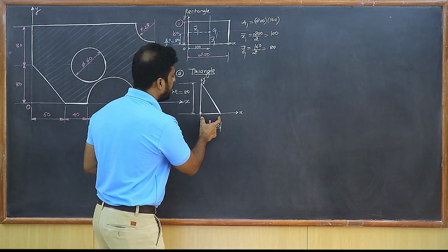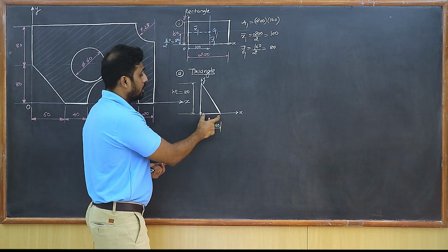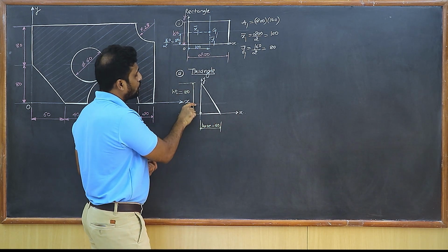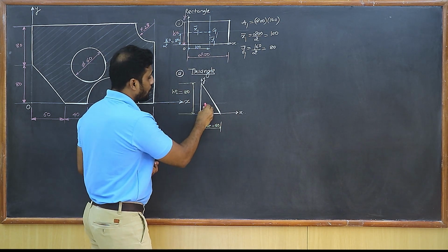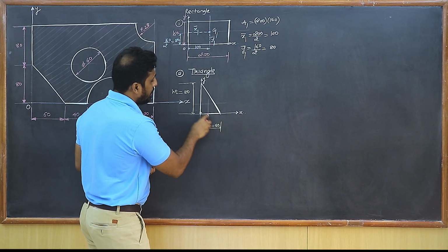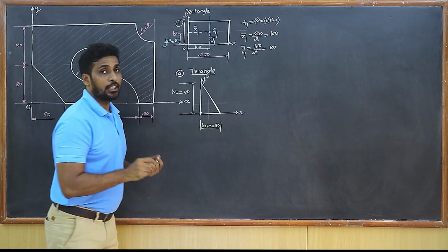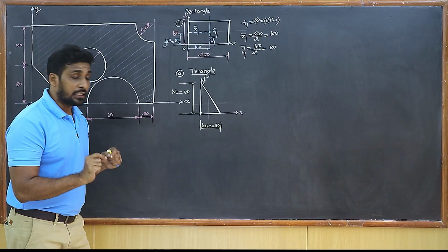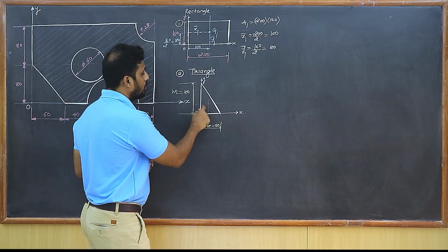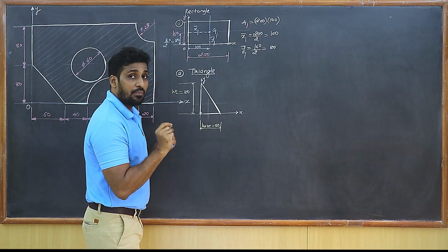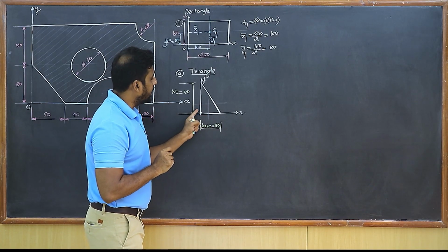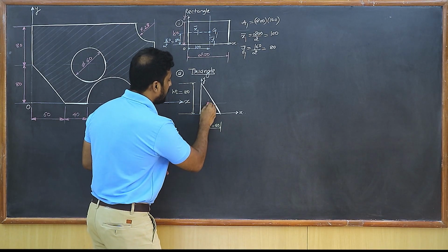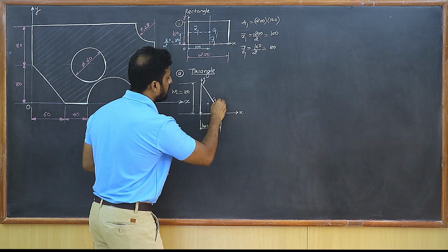I can observe here that this is one of the perpendicular sides. So draw one parallel line to this one, so that this parallel line is at a distance of 1/3 from the height. Likewise, draw one more parallel line to this particular perpendicular side. So simply draw parallel lines to the perpendicular sides such that they are at distances of 1/3 from the perpendicular sides. Always remember, the distances from the perpendicular sides must always be 1/3 of the base and the height. So you can easily observe that this is going to be the centroid, this is G2.